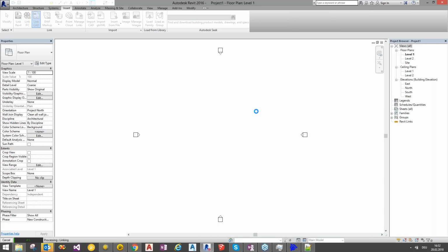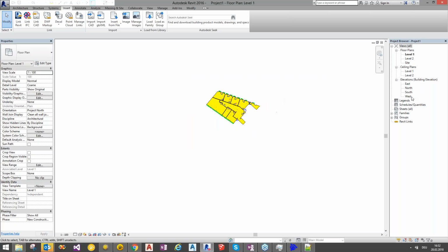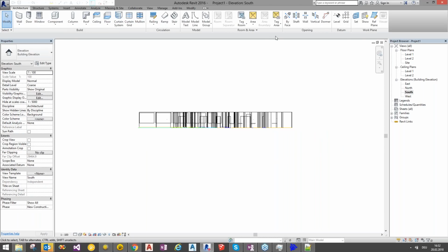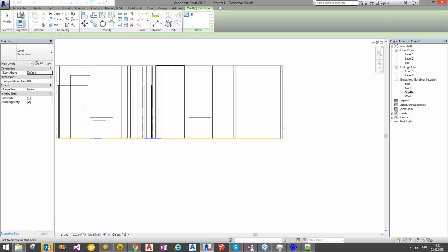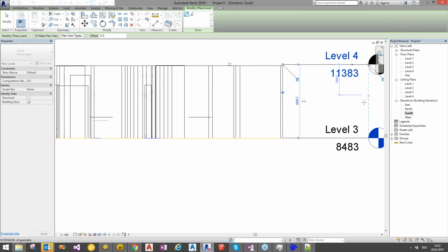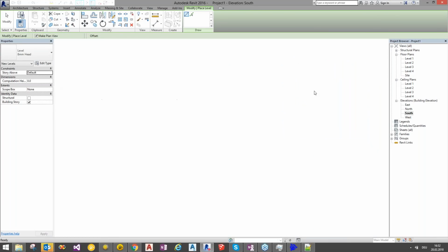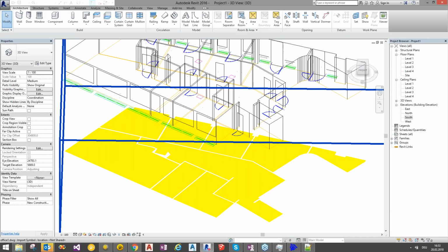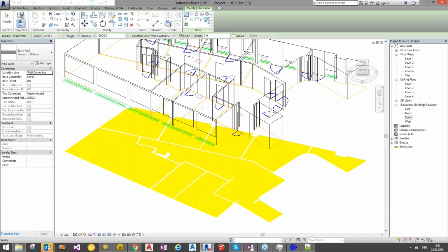So we have it in the drawing. So we see it there, and then we just need to create 2 levels to create the walls, and that's it. So we can start doing the rest. I just create it approximately just to show it very quickly. So we change to the 3D, and then we use the existing elements to create the walls, for example. So we just pick on the elements from level 3 to level 4.